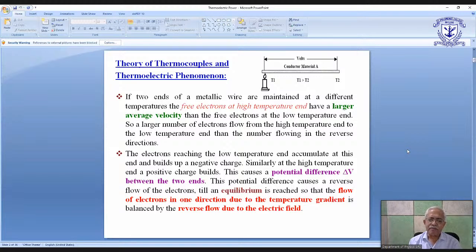So this is the basic physical phenomenon that happens, and it happens because of the temperature gradient which is created by supplying energy to the bar at one end. Okay, gradients cannot be created in steady state. You have to disturb the steady state by providing energy from outside. So that is what the small candle is doing in the figure. Okay. Right.